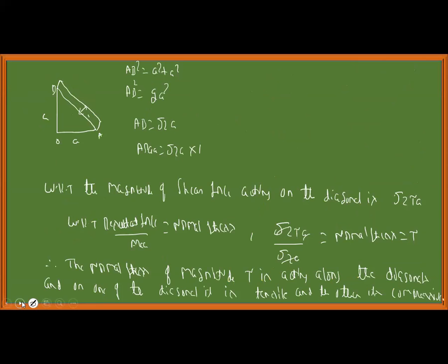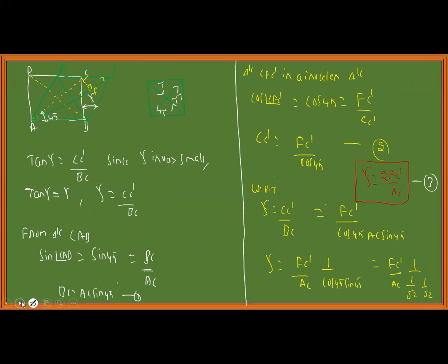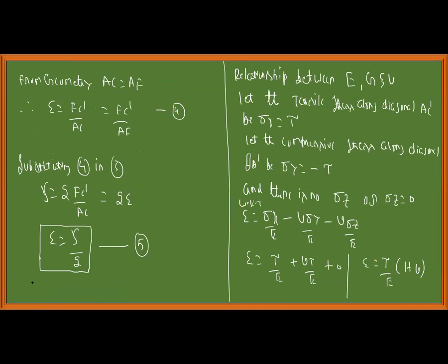After we came to know these forces, I evaluate the area. Area comes out to be root 2 a. If I divide the resultant force by area, I get the normal stress. I know the normal stress. One of the diagonals is under tension, the other under compression. Now, by geometry, we prove that shear strain is the change in angle. Change in angle is this, CC dash. Gamma is CC dash by original length BC, and we have derived that gamma is equal to 2 times CC dash by AC. That is, our linear strain is half of the shear strain.